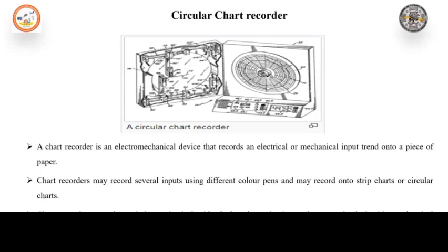In this recorder, a circular chart is used which has concentric circles ruled on it to form its scales. In addition, there are printed arcs extending from the center of the chart to the paper's edge. As the pen of the recorder is moved, it swings along these arcs. The arcs are called time arcs.